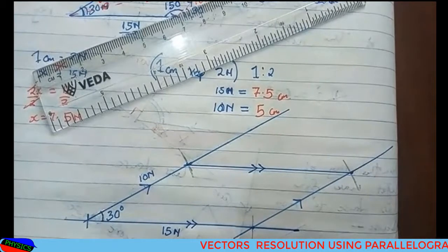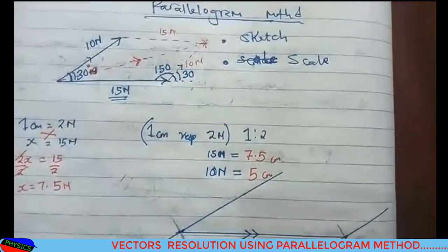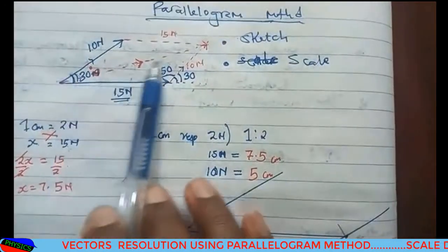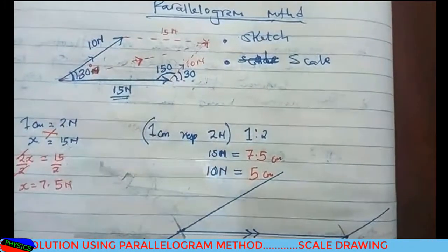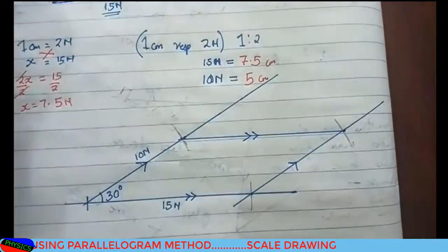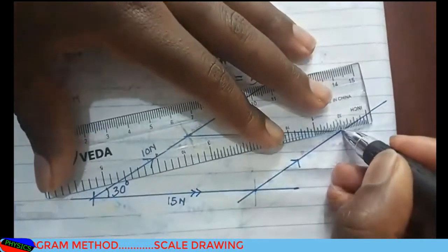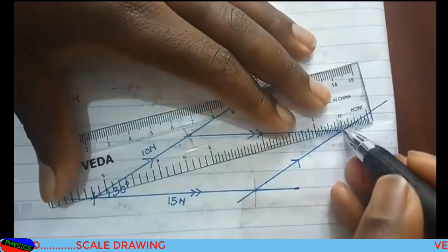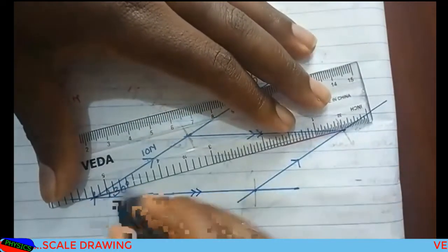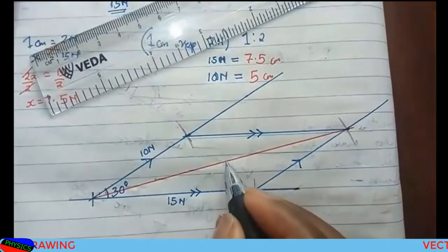The final thing I'm going to do to get the resultant vector, we said, should be this diagonal in the same direction as the other two forces. So this center diagonal. I'm going to come to my diagram here and drop my diagonal. Then here is my diagonal. So this is my resultant force.